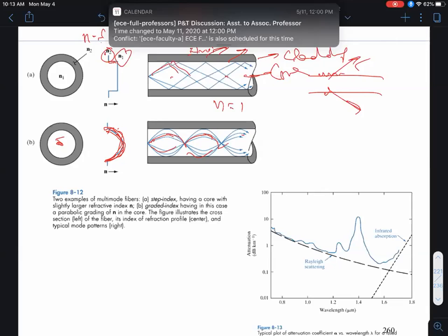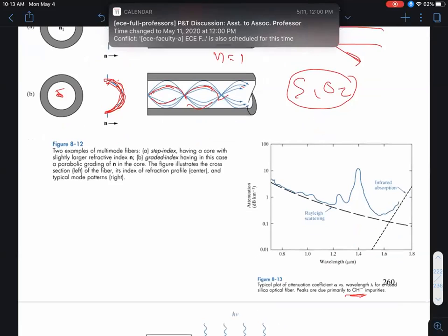Now, these optical fibers are basically made of glass, SiO2, but very, very clean glass, okay? But even if you make it very, very clean, you'll always have some scattering or absorption of the light, okay? And people have studied this in gory detail. One of the culprits is OH hydroxyl groups in glass, okay? The net upshot of that is, if you look at the attenuation in decibels per kilometer of travel of the light, shown on a log scale, as a function of the wavelength of light,